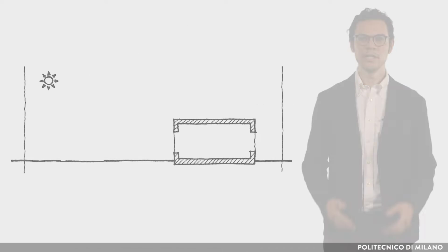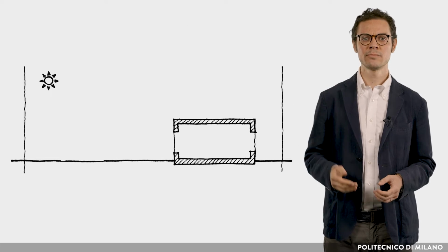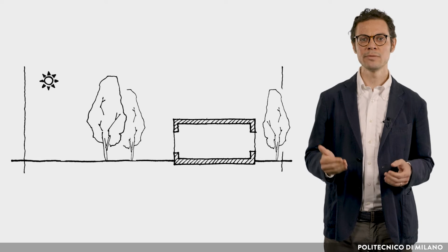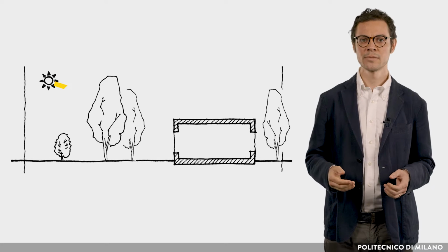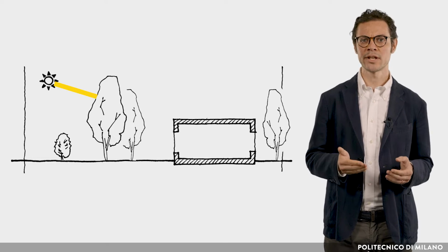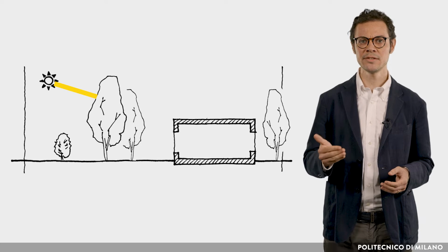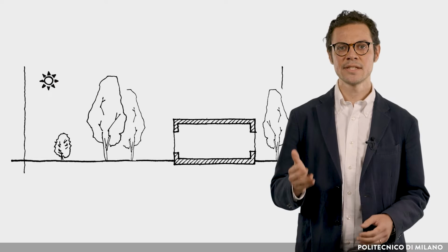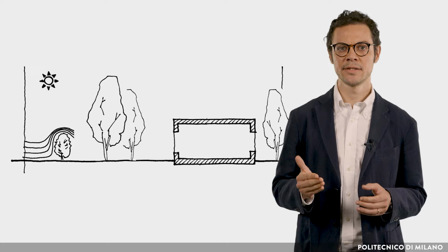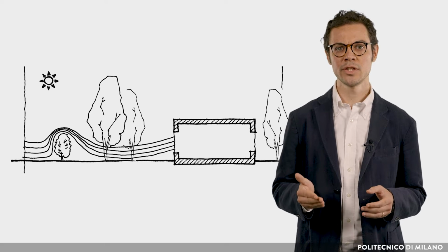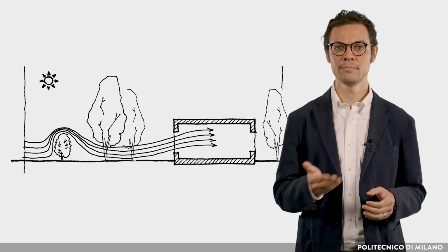systems. In order to provide sun protection, the building should be surrounded by trees, shrubs, and grass, which will absorb solar radiation, not reflecting it into the building. Trees need to be with high trunk and appropriately positioned to avoid screening of the wind.